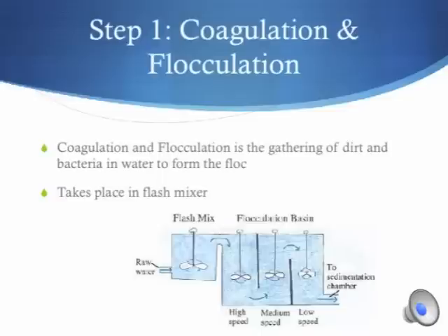Turbidity is the cloudiness of water. There are three processes to remove turbidity: flash mixing, coagulation, and flocculation. During flash mixing, particles are whirled around in water at high speed with a coagulant for no more than a minute while forming floc. The way coagulation works is by neutralizing the electrical charges on particles in the water, which then allows them to bunch together and sink to the bottom.